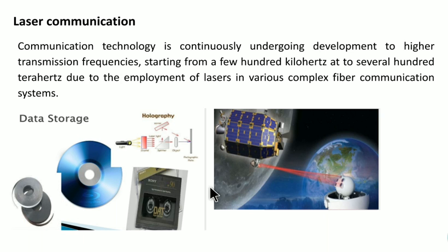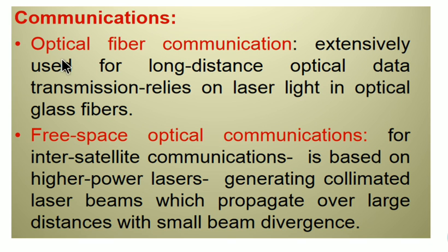Laser can be used as the transmitter source of light because the laser is monochromatic. Now free space optical communication for inter-satellite communications is based on a high power laser generating a collimated laser beam, which propagates over a large distance with a small beam divergence.